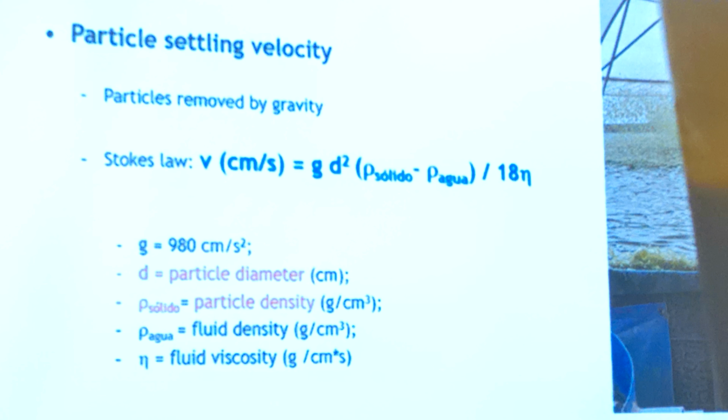So far, I will go into some theory first regarding settling devices. You can find this in any of the books that I showed you before. They basically explain how you get to a parameter that we are going to use. You can calculate the horizontal velocity using hydraulic formulas, like that one. Then you can also use Stokes' law to determine the vertical settling velocity.